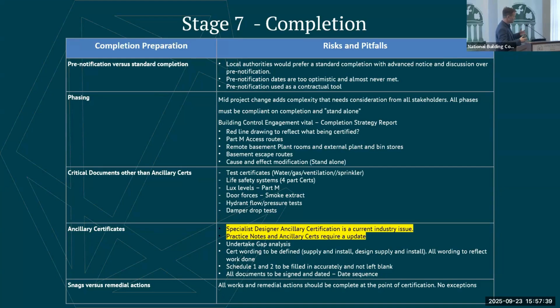What is sometimes missed is these part-time access routes. When you're complying with A to M, for whatever reason, M seems to be the one that's forgotten. But you need to be able to enter that site or that development from the main gates and access a dwelling or a commercial unit, whatever it is, as if the whole development was finished. Those access routes need to be completely done. That includes your external lighting. So if you're rushing to get a phase done, some of your external lighting standards mightn't be in place. So it's something to be mindful of. Same with crossing points, set down areas, all that stuff.